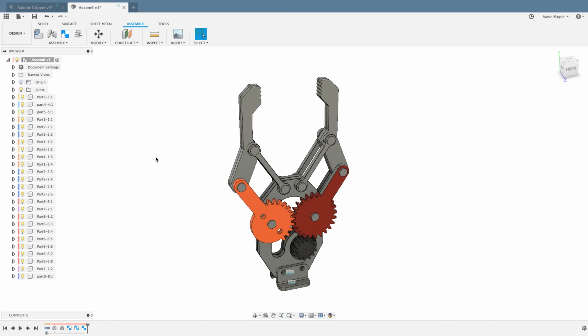So let's do a Shift J once again. And in this case, I want to start to create the rotation for this model. We'll change this type right away. You can see all the different types of joints you have access to. Revolute is what I'm going to be using here, and most of the names are pretty clear at explaining what each and every one of them does. So if you have questions of what they might do, what I'd recommend again is just try it out. Here I'll select Revolute, and I'll select this component and this component,